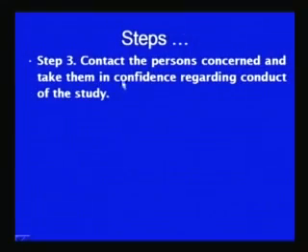And the third step in the work sampling will be to contact the persons concerned with the shop floor where a study is to be conducted, and take their permissions and the required approvals after taking them into confidence regarding the conduct of the study. So, whether the supervisor or the manager of the shop floor is there, he is to be contacted first and taken into confidence, so that he can be informed about the kind of study which is to be conducted in the shop floor, to see the percentage of people or machines working and quantify